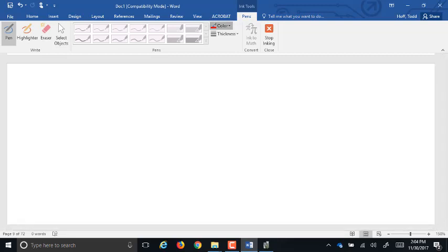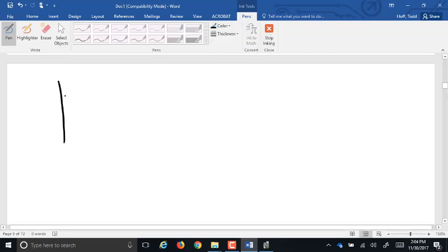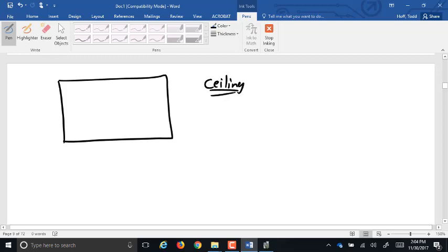The last thing I have for you guys is let's do the ceilings. Let's say we've got a 36-foot by 50-foot house. For ceilings, we need to find the floor area. Why would we find floor area? It should be the same as the ceiling area, unless you have vaulted ceilings, which would be the only difference.